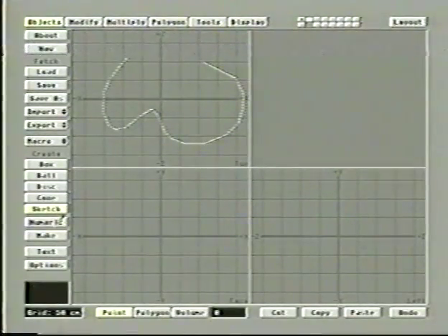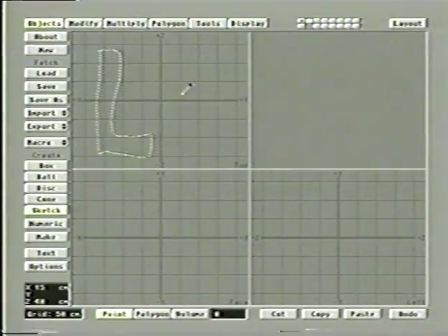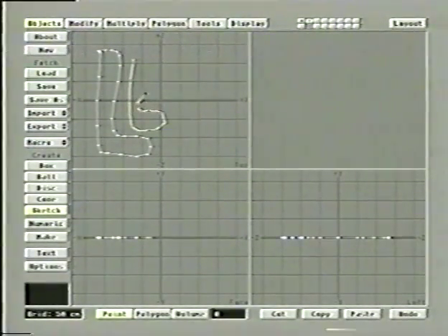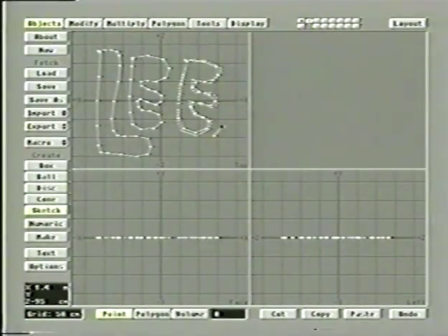You notice, let me just undo what we did here. If I go to numeric and pick polygon, now I can draw out something like this, hit make, and it approximates the shape, but it actually makes it a closed figure. So I can do really bad text like this, but obviously you can use this to create a number of shapes. And again, this is actually a fully closed polygon. Now, we usually use it with curve, though, because usually we use this for object creation.